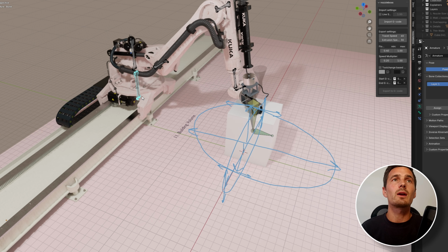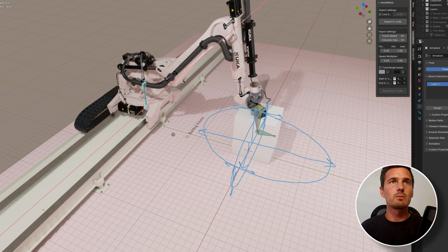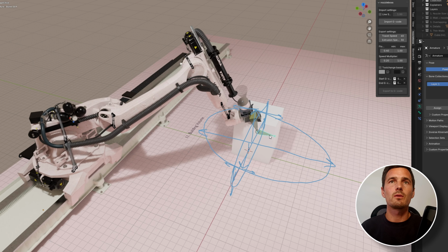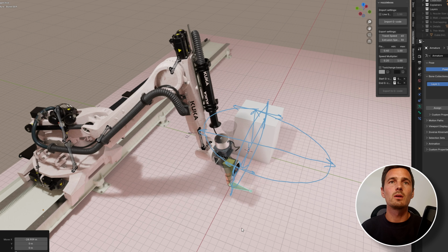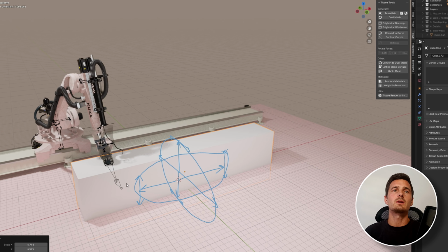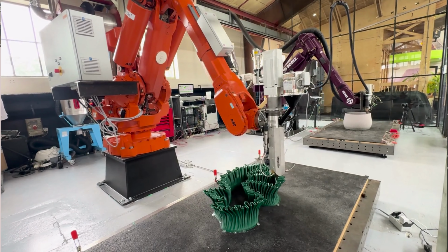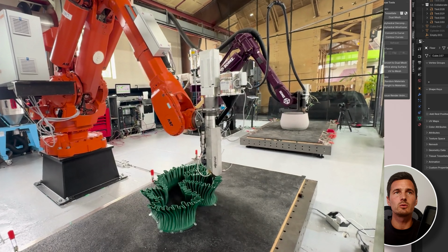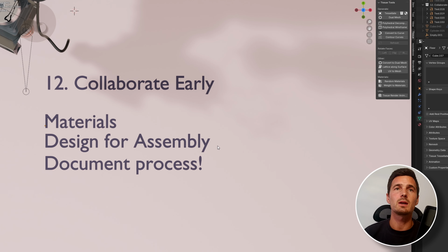This is different for every setup, because some setups, for example, can move over the X direction, and that means you can scale way further over the X direction. Service bureaus or manufacturing services all have their different kinds of systems, which have different settings and translate to different design rules. So best practice is that if you are thinking about designing something for a robotic system, include them early into the process.